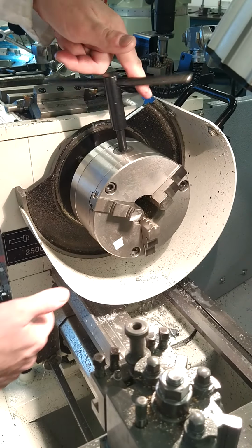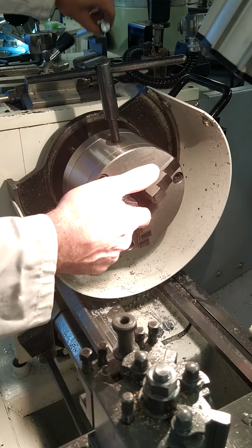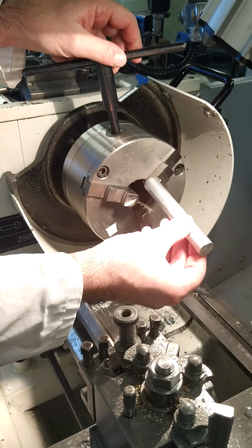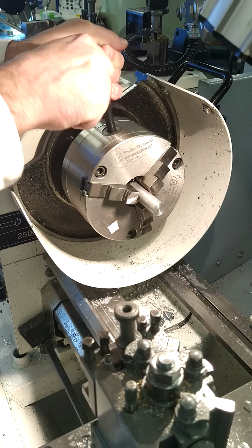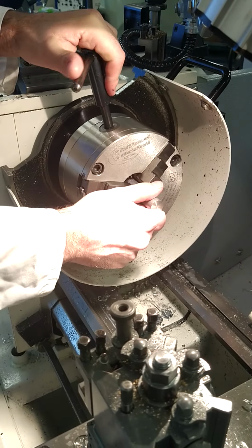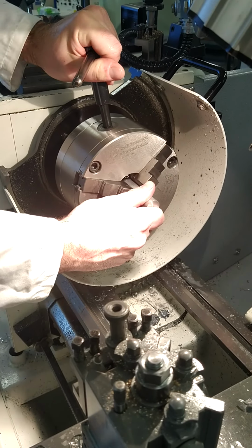So you put your material in here for gripping. If you want to put your material inside, that is going to be your diameter 25 material, according to our formula. We're popping that into position. So we're going to set RPM for turning that down. We'll have the material in position, and we'll slide an overhang there of approximately 30 millimeters.